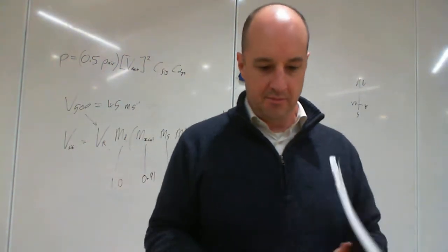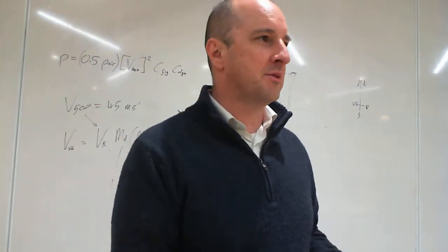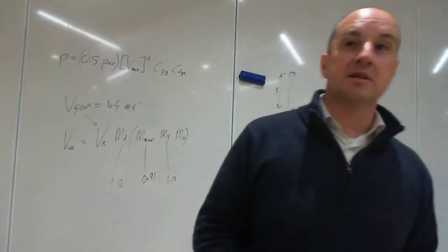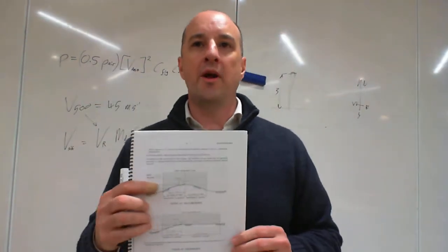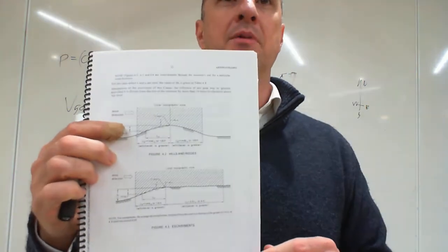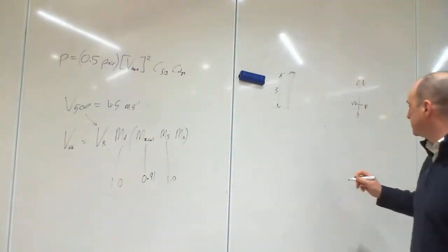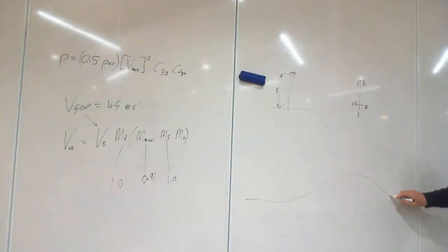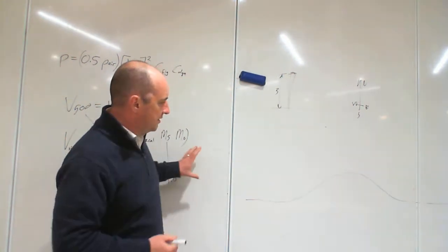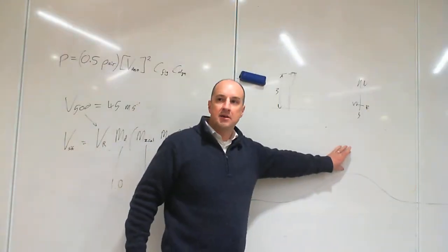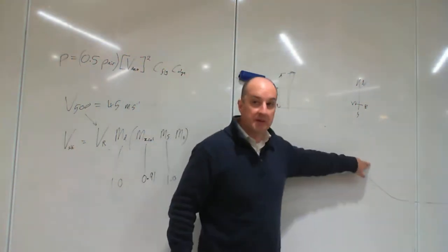Okay, the next one is the MT, which is the topographic multiplier. This is probably the hardest one to work out. When you have wind blowing over a hill, okay, the wind is blowing all this way. There's the ground, and you have this hill like this. As the wind blows along here, it compresses here, which increases the effective pressure, increases the speed of the wind over the hill.